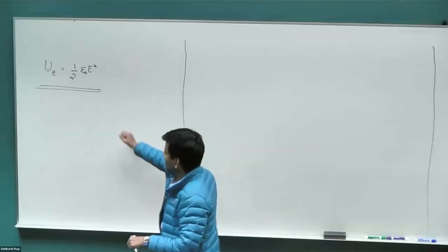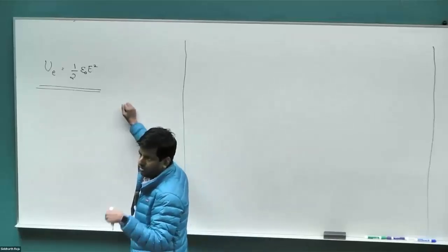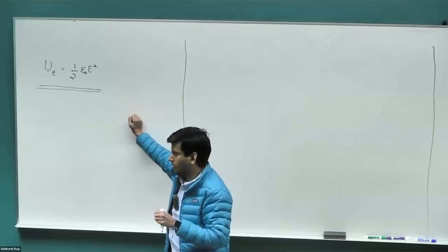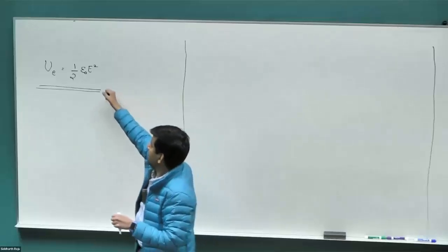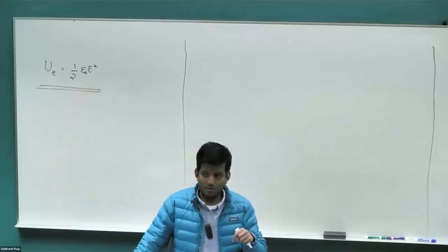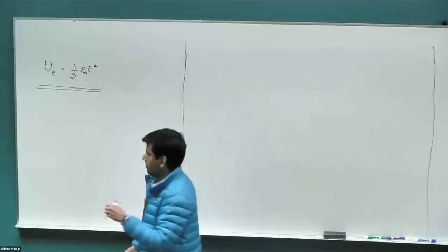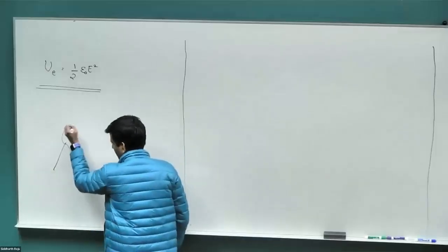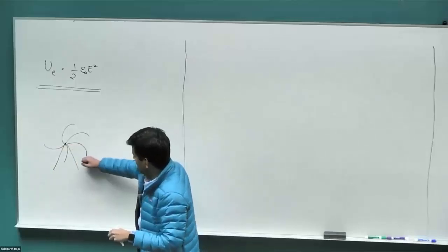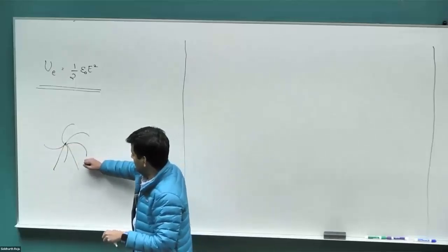And the same thing happens even in an electrostatic motor. There would have to be some air gap medium that separates the stator and the rotor, and then energy transfers to that medium. If this electric field is too large, the medium itself will start to puncture. That's what we saw in Andrew Gordon's motor, right? Where we had this tower-like arrangement and we had this pinwheel structure. And what this was doing is basically puncturing the air medium and then using the ions that were generated to